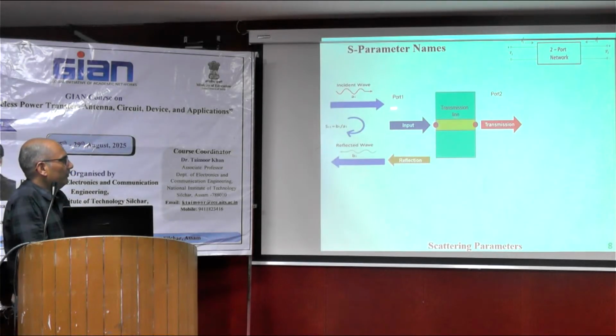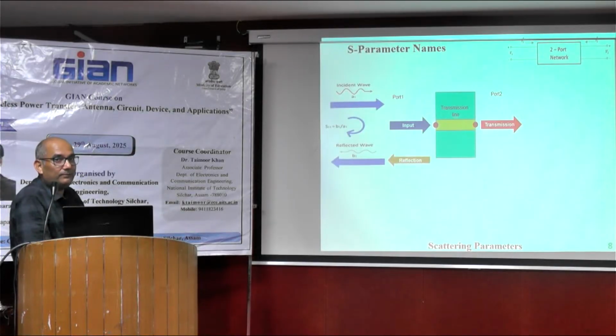That is port 1 and port 2, this is the incidence. Then the reflection from port 1 will be like this. Power is incident, a certain amount of power will be transmitted forward, and the difference of these two is due to the mismatch between this side and the impedance at this point. Because at high frequency, we need to be very careful about the matching.